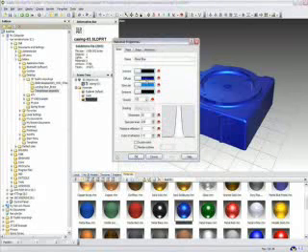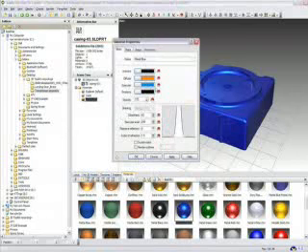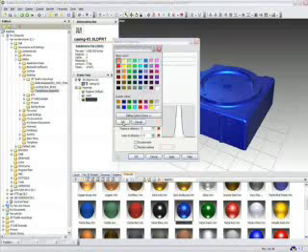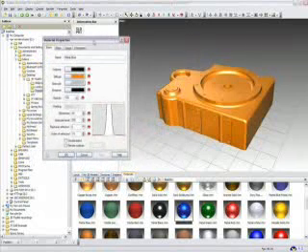By selecting the diffuse color, you can change the actual color of the material. In this case, I'll select one of the default basic orange colors. I also need to change the specular color to a neutral color so it doesn't reflect the light in blue. For this example, I select a neutral gray. As you can see in the viewport, the object is turned from metal blue to metal orange.